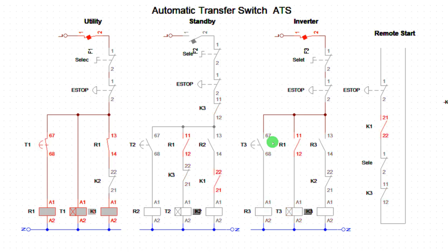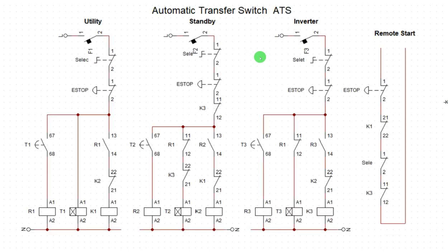You can see that mains has knocked off both inverter and the genset. This one has taken over. So this is the prime. Look at it. Look at their contact. You just disable them all until this one goes inactive. Now mains has gone out. Utility has gone out. Inverter has taken over. You have seen that this one is now second priority. All right. Okay, so we are done with our three sources of power.